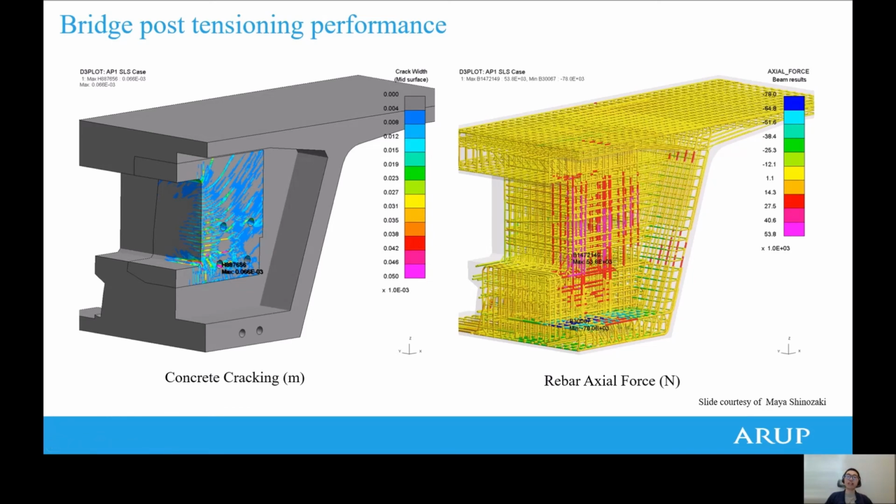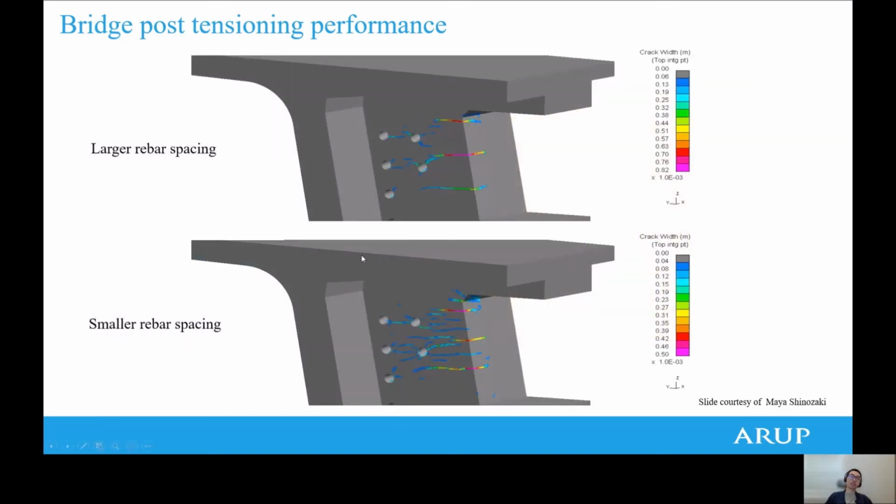By modeling everything in detail in LS-DYNA, it is possible to predict the general pattern and size of the cracks and their multi-axial stress states. And this really gives a very good indication of strength and ductility for the elements in question. And then a sensitivity study was also conducted on the model to investigate how the different rebar designs, for example, and the loading sequence can affect the responses and the crack formation. This provides significant value to inform both the design and construction sequence planning.